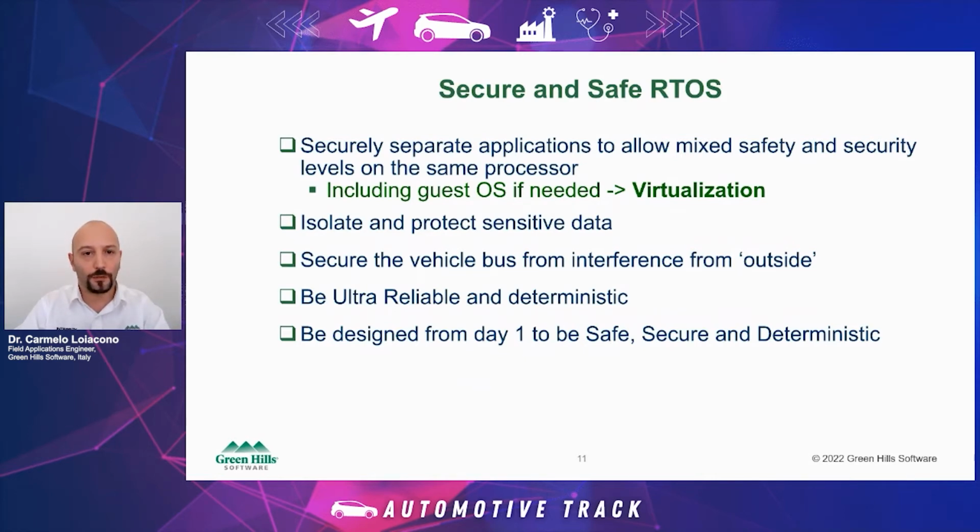like INTEGRITY from Green Hills Software, allows us to separate applications and run mixed-criticality components on the same system. So components that have high security or safety requirements, along with components that do not have those requirements.